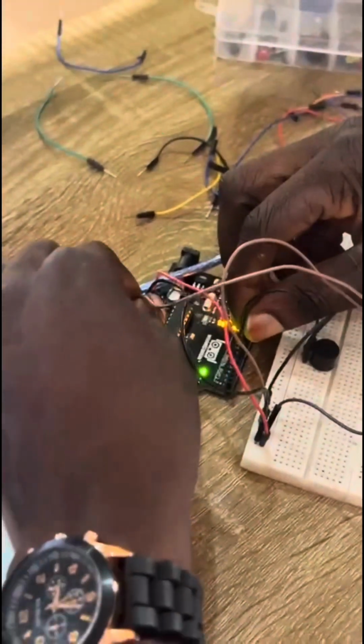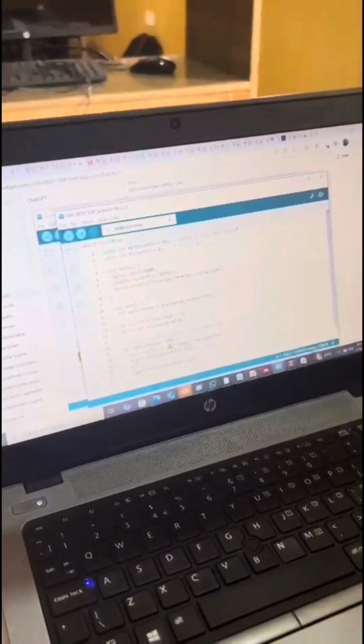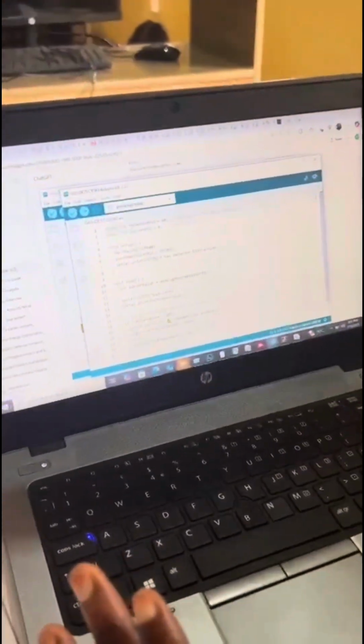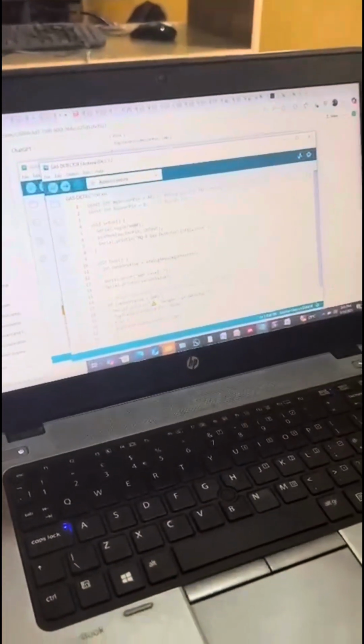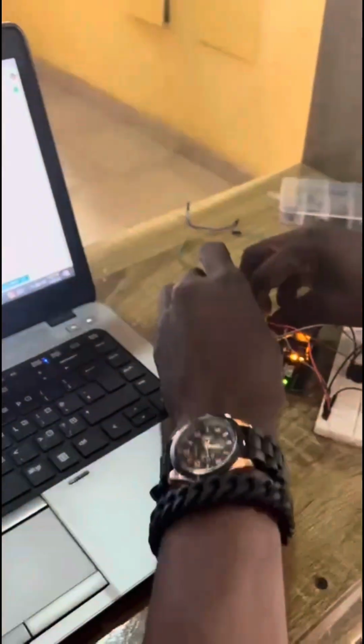Now, you are supposed to understand that if I want to do anything on this Arduino board, I must first declare it. So now I'm using only 2 pins. I'm using the pin 8 and A0. The A0 means analog input 0. These are digital pins. These are analog pins. I think those have been explained to you last semester. Then we are using 5 volts and ground. We don't need to declare that. Those are power sources. But these pins, digital pin and analog, we must declare.